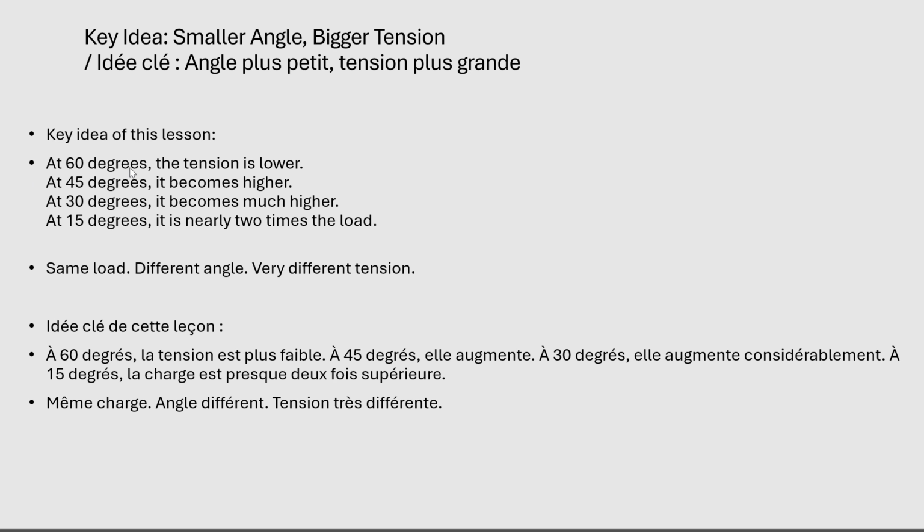At 60 degrees, the tension is lower. At 45 degrees, it becomes higher. At 30 degrees, it becomes much higher. At 15 degrees, it is nearly 4 times the load. To sum up, same load, different angle, very different tension.